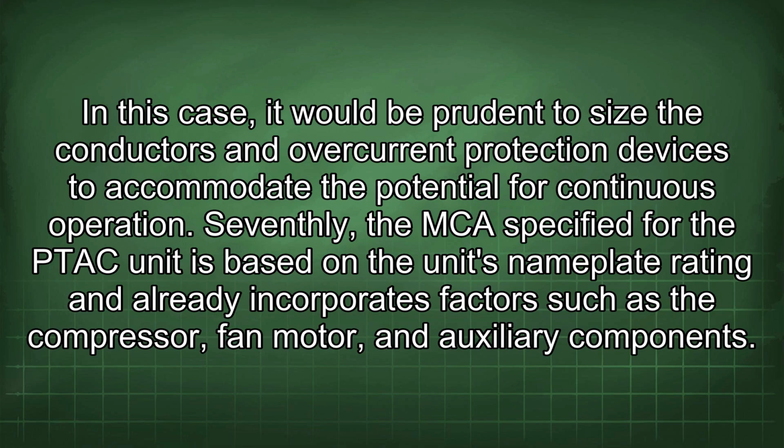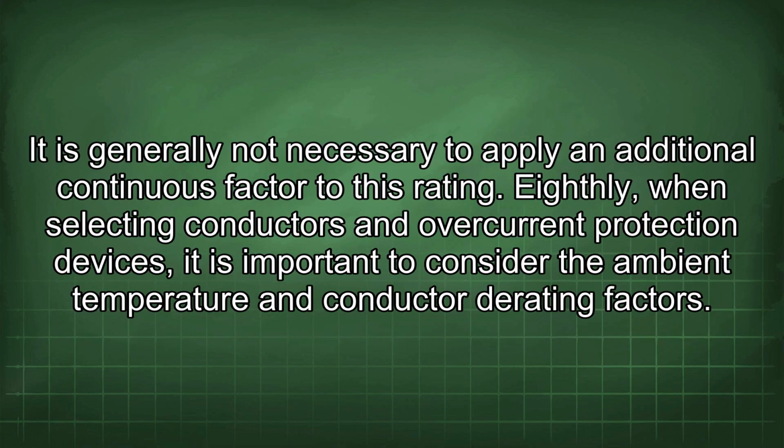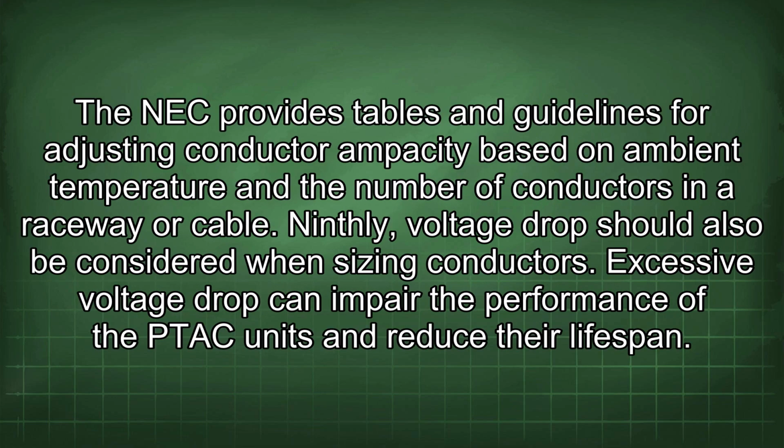Seventhly, the MCA specified for the TAC unit is based on the unit's nameplate rating and already incorporates factors such as the compressor, fan motor, and auxiliary components. It is generally not necessary to apply an additional continuous factor to this rating. Eighthly, when selecting conductors and overcurrent protection devices, it is important to consider the ambient temperature and conductor rating factors. The NEC provides tables and guidelines for adjusting conductor ampacity based on ambient temperature and the number of conductors in a raceway or cable. Ninthly, voltage drop should also be considered when sizing conductors.